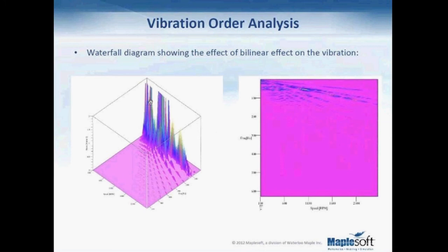You can also plot the individual shear stress or vibratory torque for each order in a waterfall diagram, as I'm showing on this slide. For example, the first plot shows the maximum shear stress in the z-axis for the 24 harmonic orders.